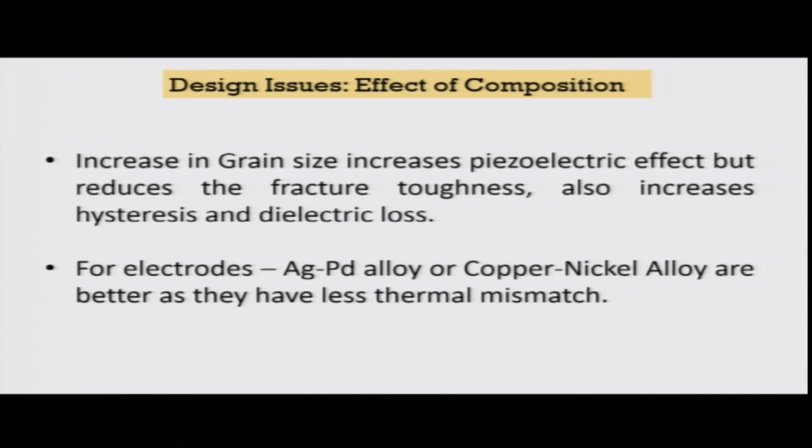There are also effects of the composition of the system, because the grain size of the piezoelectric material has paramount importance. If you increase the grain size, the piezoelectric effect will increase. I told you that a single crystal gives you the maximum piezoelectric effect, but it will reduce the fracture toughness. Also, the grain size would affect the hysteresis and the dielectric loss.